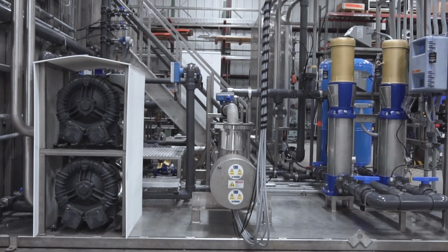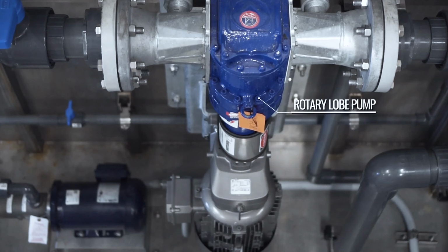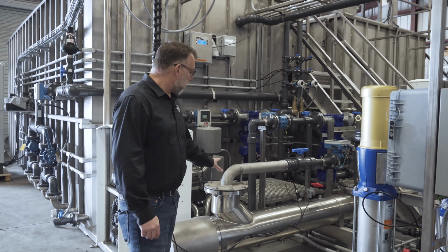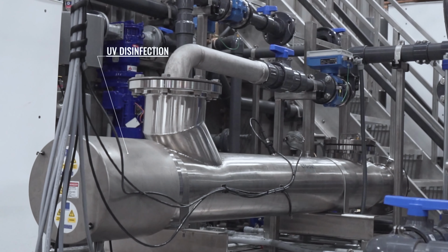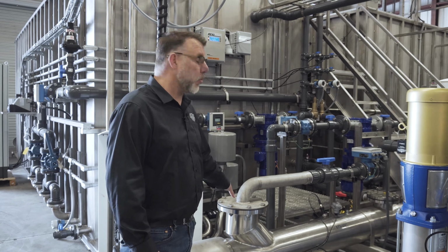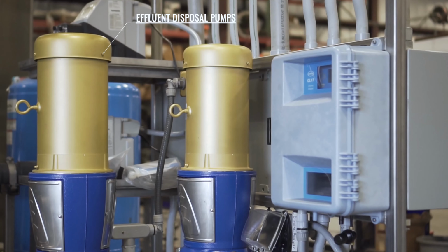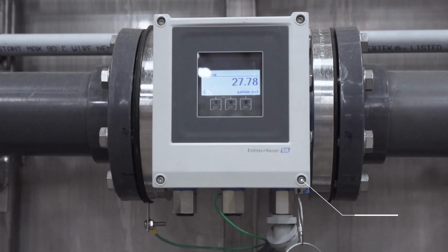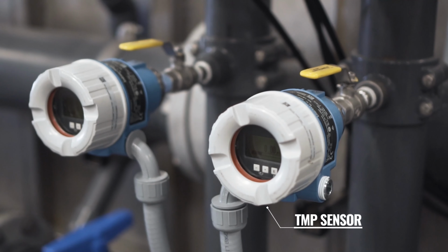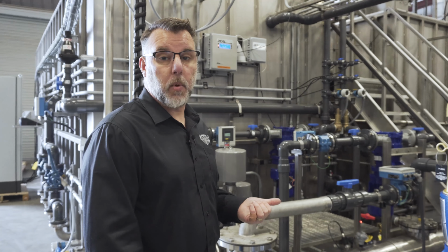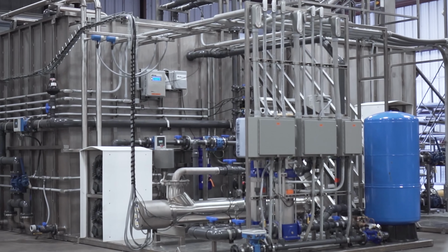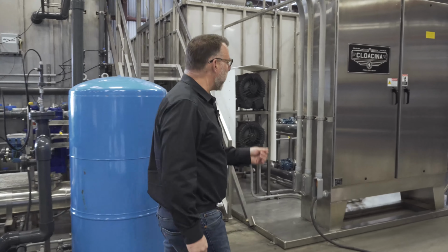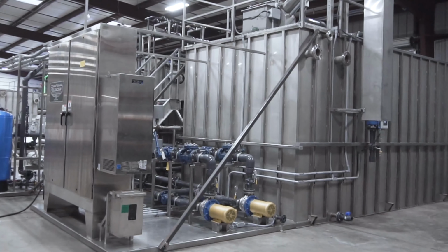On this side we have all of our membrane equipment including blowers and permeate pumps, control equipment, and pressure overloads. This system also includes integrated ultraviolet disinfection equipment, which is Title 22 validated, and effluent disposal pumps. You'll notice sensory equipment on this skid as well. We are monitoring flow and pressure of each membrane cassette independently, as well as effluent flow and pressure on the effluent pumps.